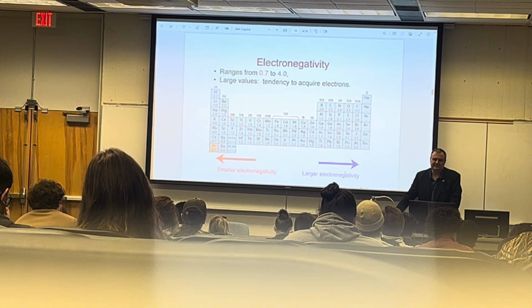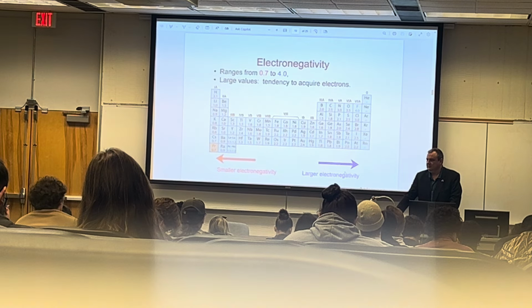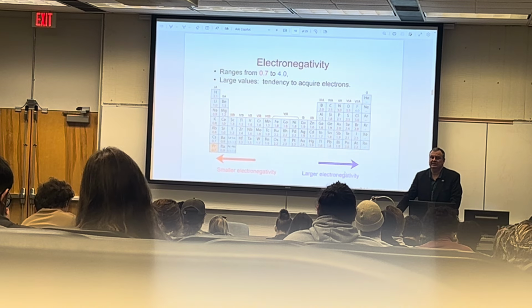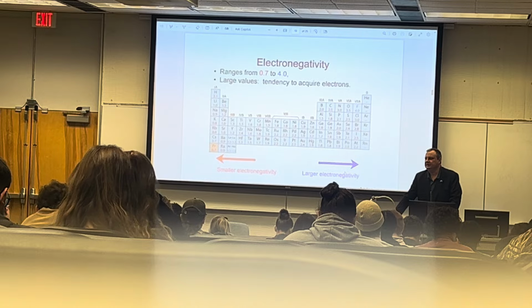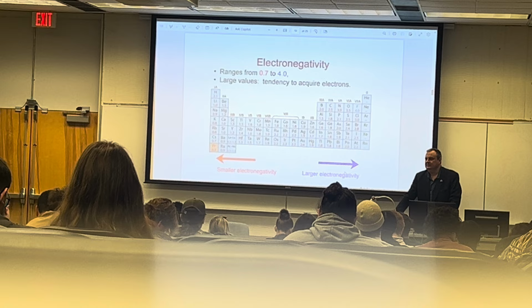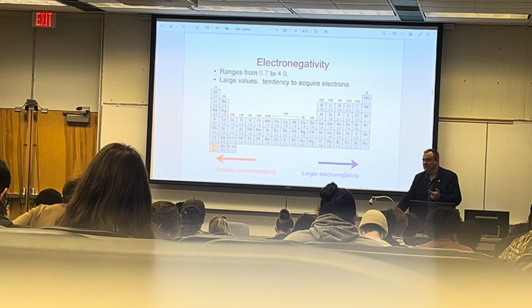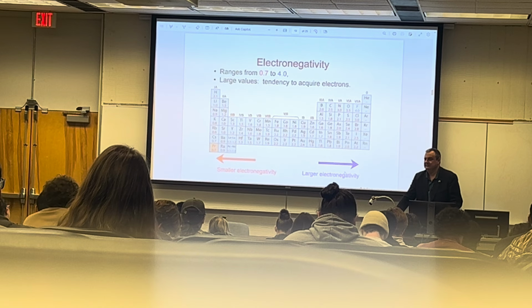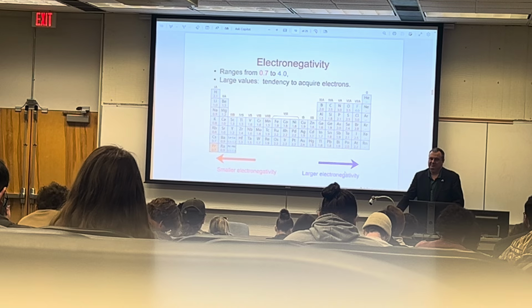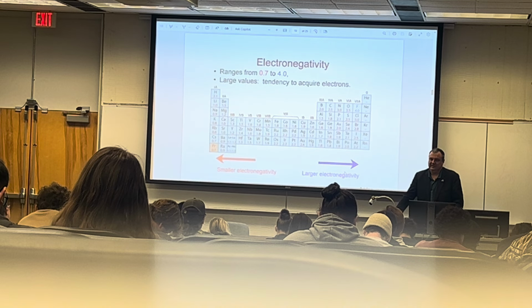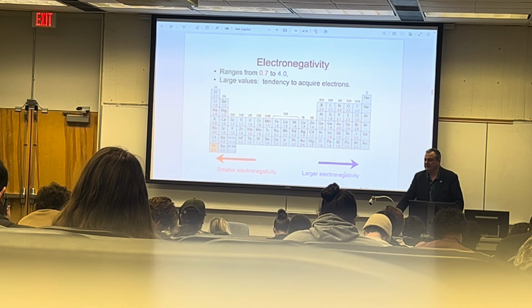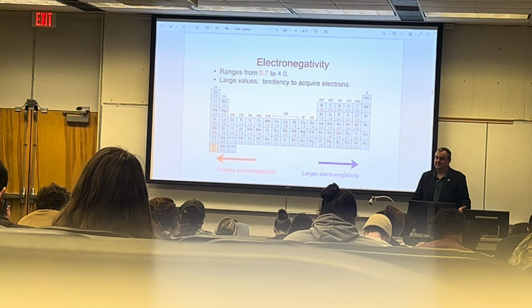And if you're too precise, for example, if you're measuring temperature and it's 1,000 degrees centigrade, and somebody gives you a number 1,000.001 degrees, what does that mean? Do you think you have the resolution and the accuracy to measure thousandths of a degree at 1,000 degrees? What do you think? Probably not. But how do you know where you're supposed to be rounding or not? I guess it comes with practice.